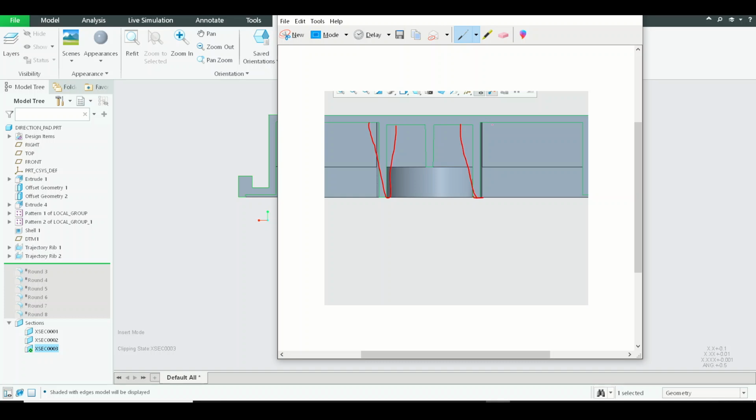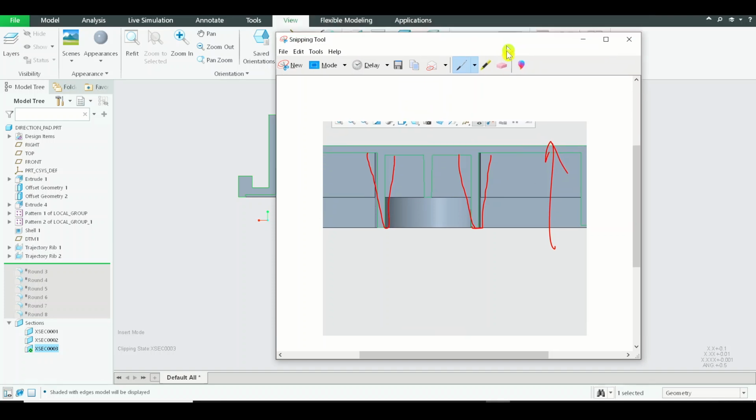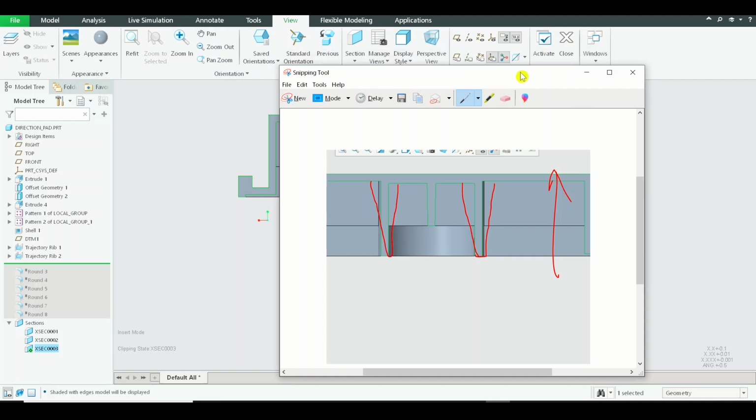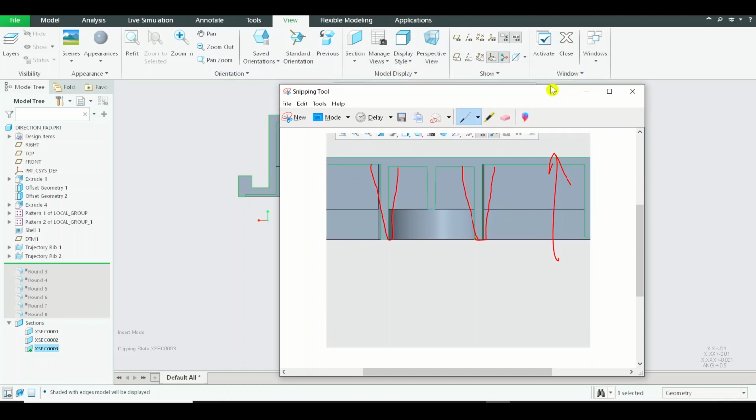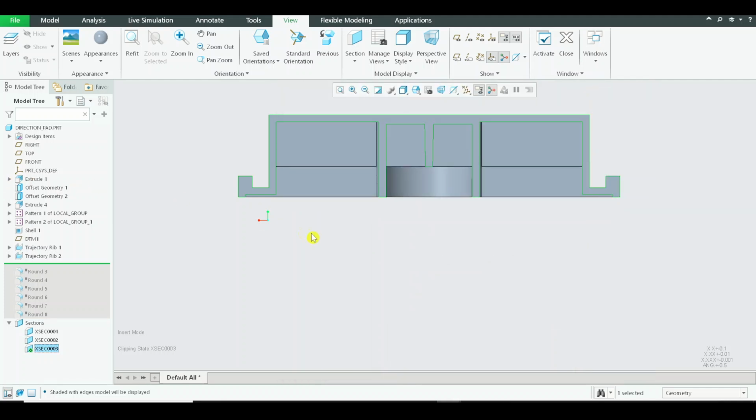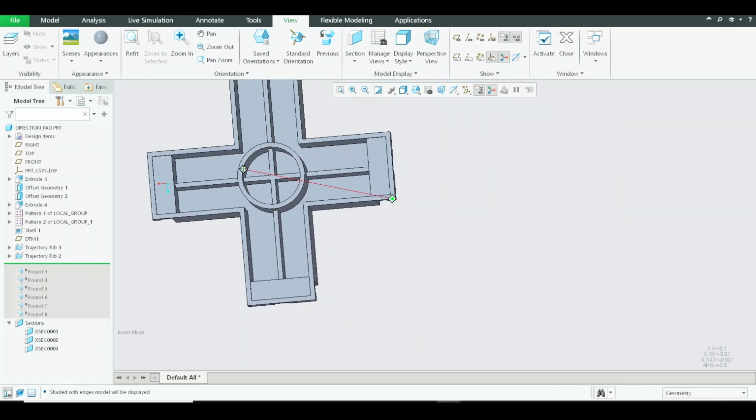Thickness of the wall like this, because when you're pulling it in upward direction, this can easily be pulled. It can easily come out from the cavity what you have, or the core what you have. Okay, if this is the core, it can easily come out from that core, right? So this is the reason we have to analyze what is the direction, then we have to create the drafts in that direction. Okay, so we will be adding the drafts now.